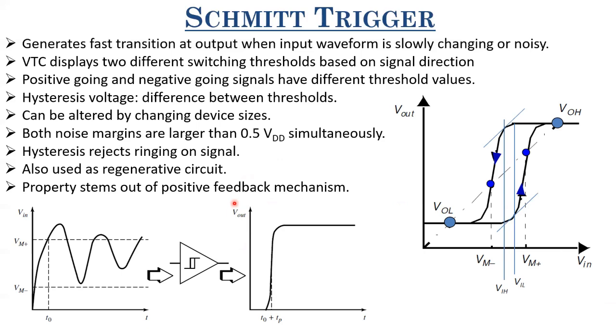You may have heard in your analog circuit design course that negative feedback is very important. Positive feedback leads to unstable systems. But you see how positive feedback has been used in digital circuits to our own benefit. The Schmitt trigger circuit, or even your entire batch of sequential circuits, registers, use a positive feedback mechanism, right? So positive feedback is also not bad. In terms of digital circuits, positive feedback is not at all harming.